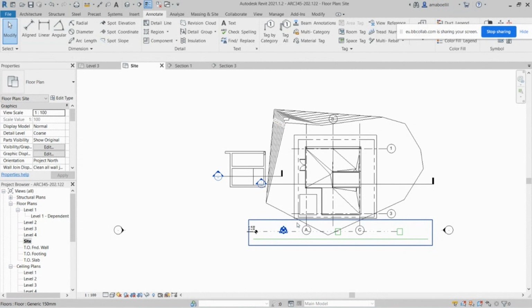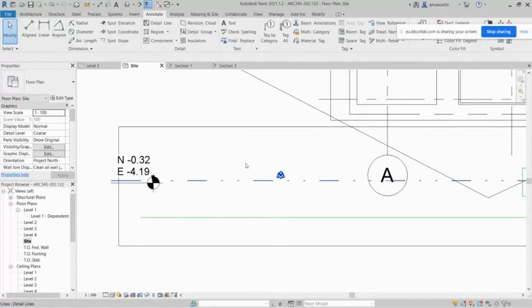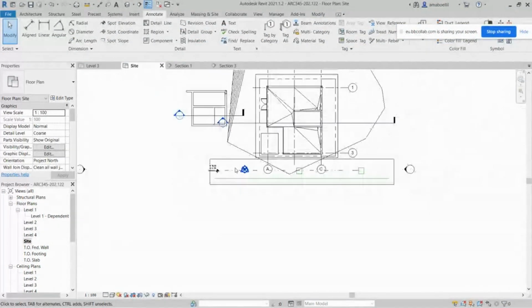Sometimes the government bans the drainage of rain into the sewer system, in order not to overload the sewer system with other things. But in general, the correct way is that the street in the cross section is highest in the middle, and lowest at the edges, so that whenever it rains, the water will run off to the sides, and you will have some holes in the curb in order to drain the water away from the streets.